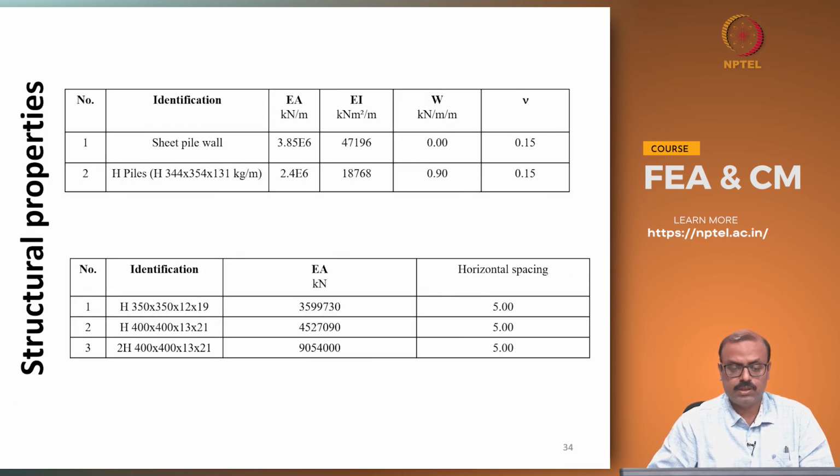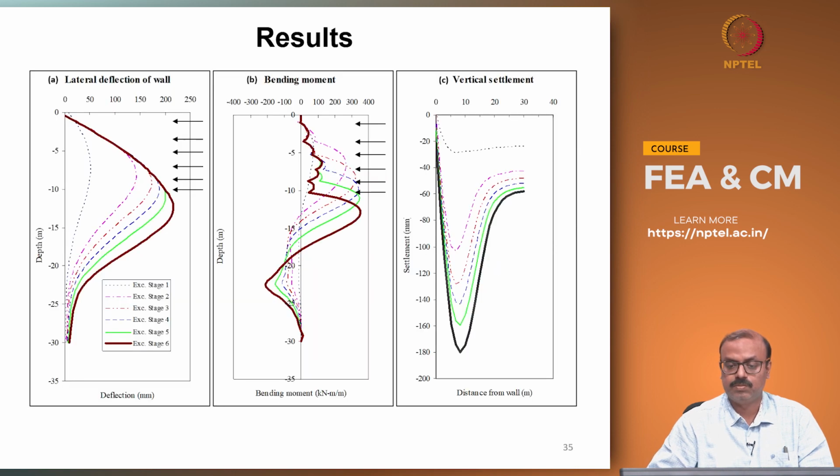So, these are the structural properties of the sheet pile, H piles and the struts. Essentially the struts are axial members, so we have given the axial rigidity. For sheet piles and H piles, we have given both the axial rigidity as well as the flexural rigidity.